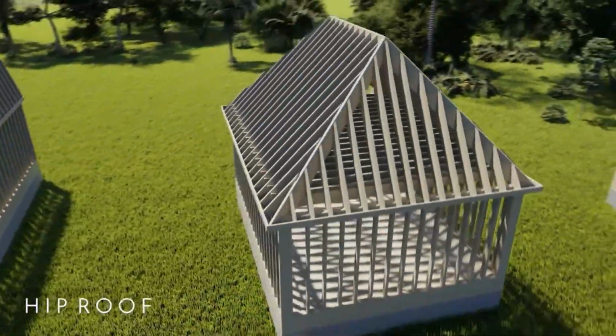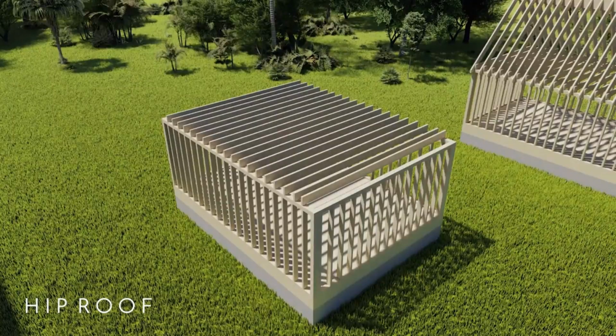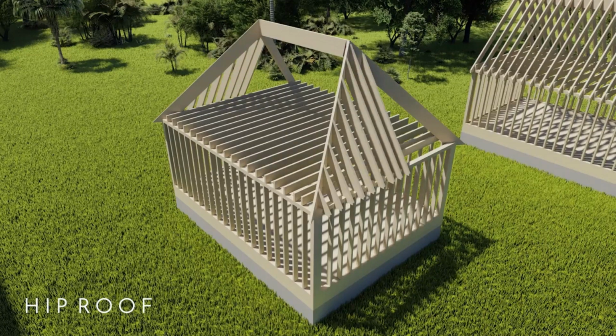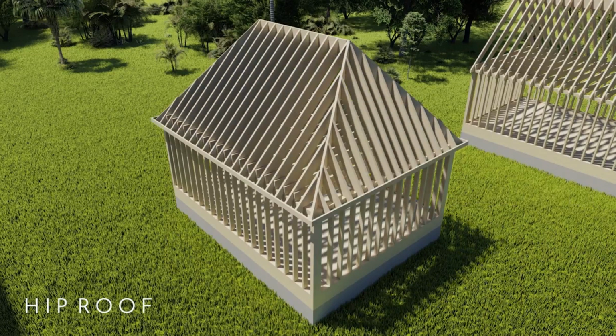Alright, so now let's look at the hip roof. So this is a little bit more complex, but not really. The posts, instead of starting at the ends, start more in the middle. Then the ridge is placed, and then these hip beams from all four corners connect to the end of the ridge. And then we have all these rafters that fill in these four separate bays. And then the fascia board caps off all the ends of the rafters again.